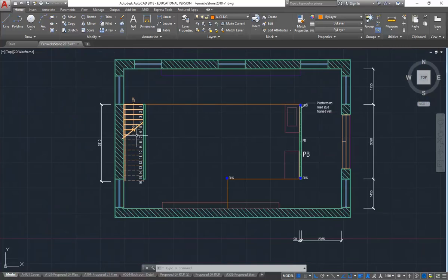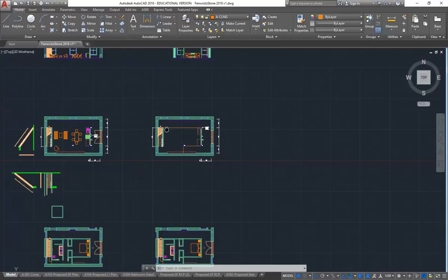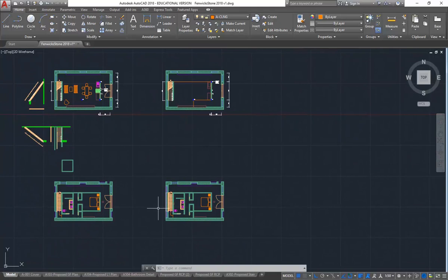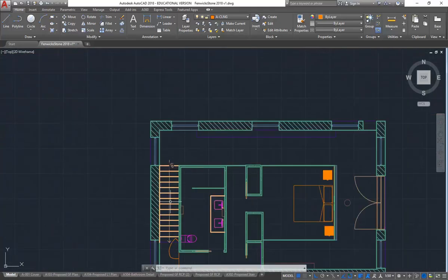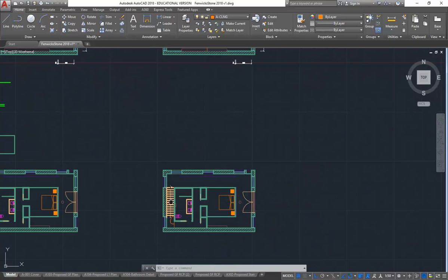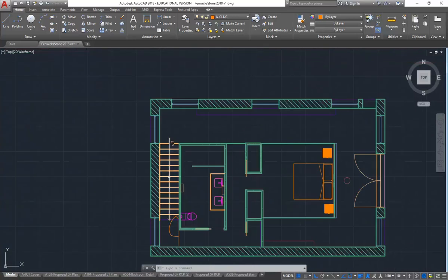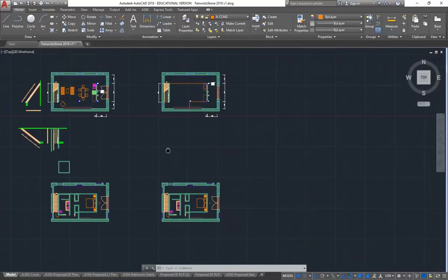In this case, you might be able to get by with the smoke alarm on the upper level, where the stairs rise up to the bedroom. But it's probably not a bad idea to also have one on the ground floor if you've got a design like this. So you may have one between the stairs and the living space. It could be in this area or even over here. I think with my design it would be okay just to have it on the upper level, above these stairs. But again, it really depends on your design.